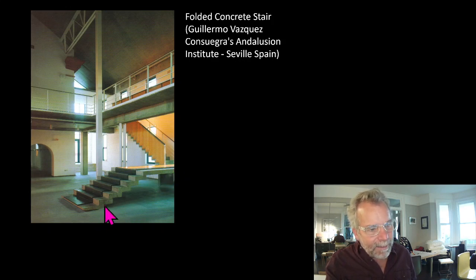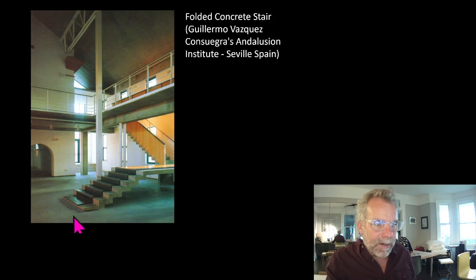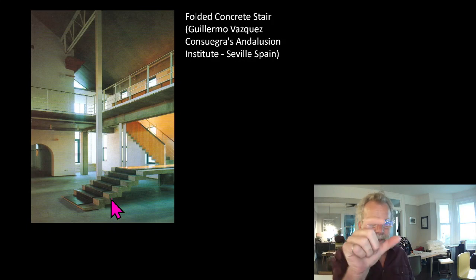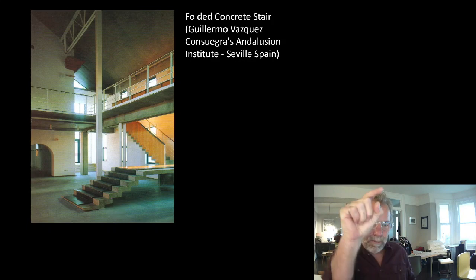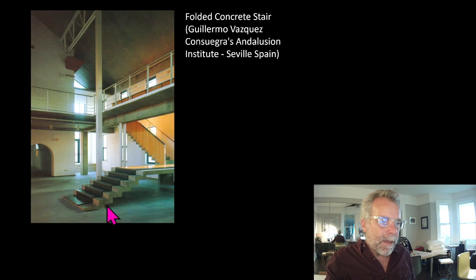The challenge is that we've got to bend our bars. We need that full 150 millimeter thickness. We can't run a single straight bar up the middle, because then our thickness is measured across the diagonal from the inside to the inside corner, and suddenly we've got very, very little thickness.